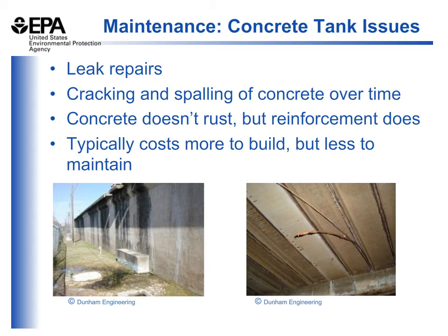Concrete tanks are pretty durable, and the concrete itself is not going to rust or corrode, but the reinforcement or rebar will. This is evident in both the photos on the slide. If the exterior or interior of the tank isn't maintained, corrosion or pitting in the concrete can expose the reinforcement or rebar and cause it to corrode. You're also going to watch for leaks in concrete tanks, make sure they're repaired, and pay attention to potential cracking or pitting over time.